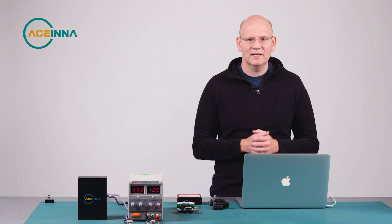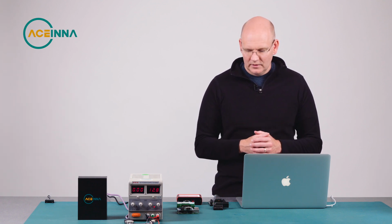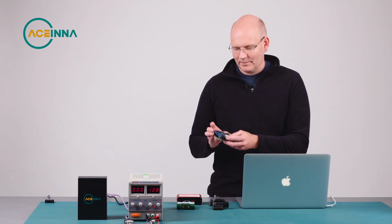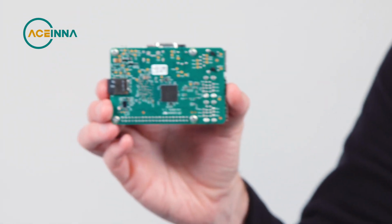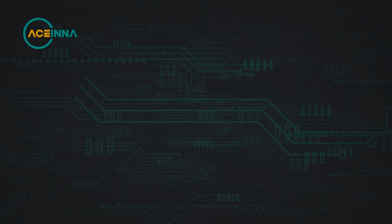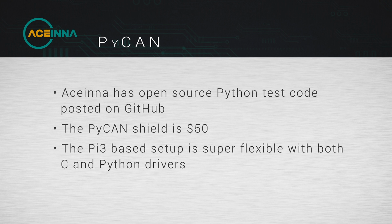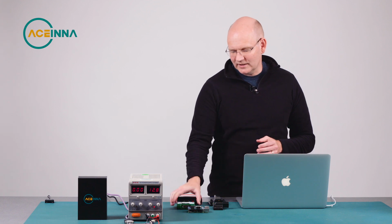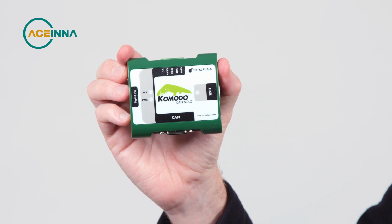Now, before we get started coding, let's talk about debugging CAN applications. PCs and Macs do not have a CAN port, so we need some external hardware. There are many options, and I'll show you 3 of them. The most developer-friendly is the PyCAN Shield for the Raspberry Pi 3. ACEINNA, in fact, has some open source Python test code which uses this hardware, and we've posted that on GitHub. The PyCAN itself is only $50, and the Pi 3 based setup is super flexible with C and Python drivers available.